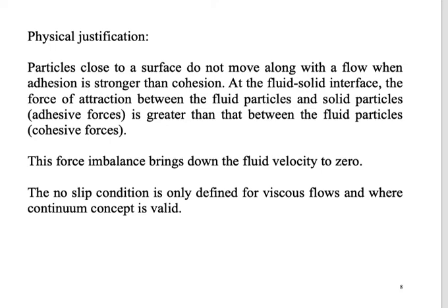Particles close to a surface do not move along with the flow when adhesion is stronger than cohesion. At the fluid-solid interface, the force of attraction between the fluid particle and the solid particle, the adhesive force, is greater than that between the fluid particles, which is the cohesive force. The force imbalance brings down the fluid velocity to 0. The no-slip condition is only defined for viscous flow and where the continuum concept is valid.